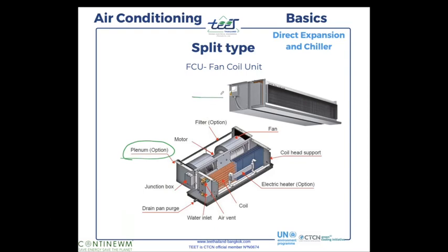So this is a photo. So the air here is blown this way and sucked from there, okay? In general, when it's well done, here is ducted. That means you have a big duct into a specific material to bring the air to the room in different places, okay? And on the back, you have this plenum. The plenum is a kind of box where you can put the filters.